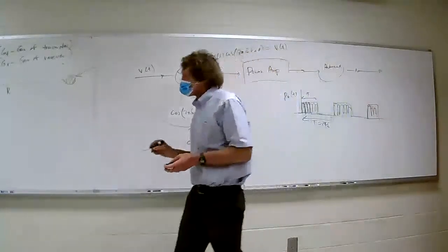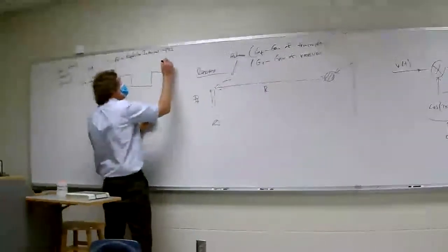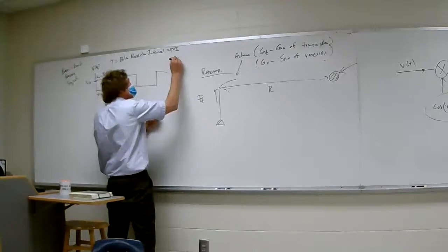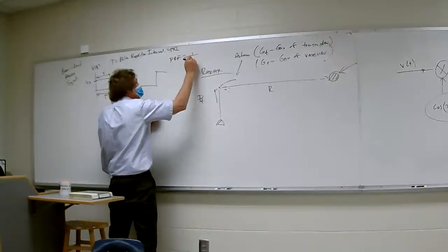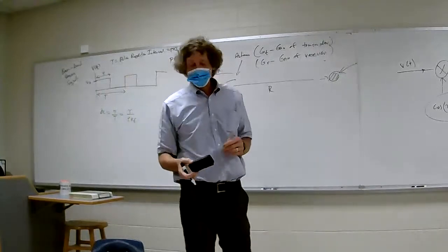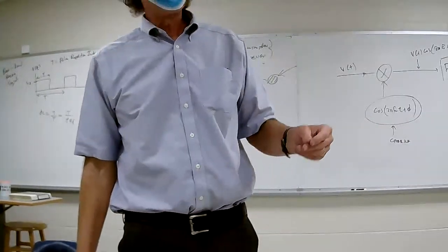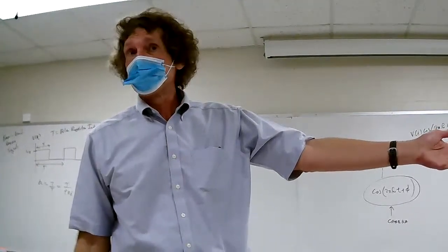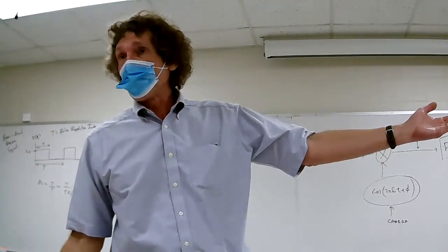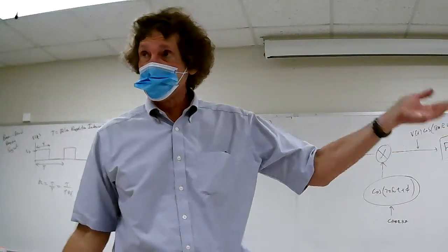I should make one other note. Whenever you read or talk about radar, they often talk about the pulse repetition frequency, which is 1 over PRI. Think of it this way: 1 over 60 is the actual period of the wall voltage, but normally when we talk about wall voltage, we talk about 60 hertz. Do y'all follow me? Same way here.